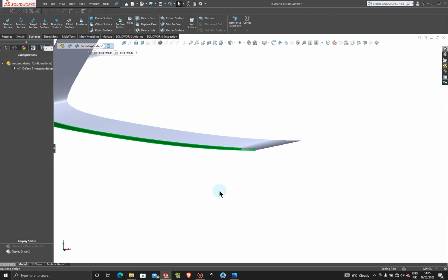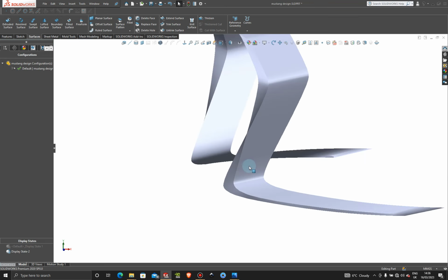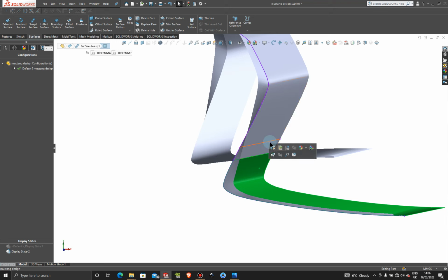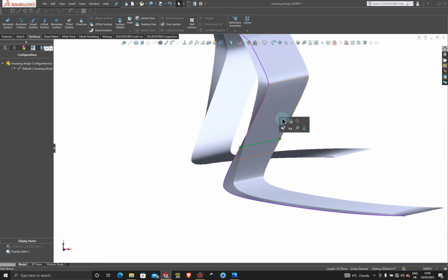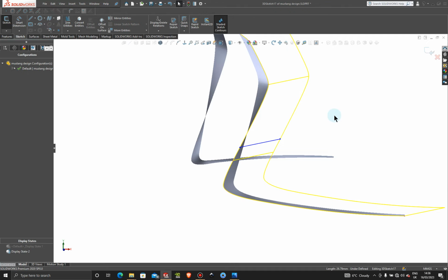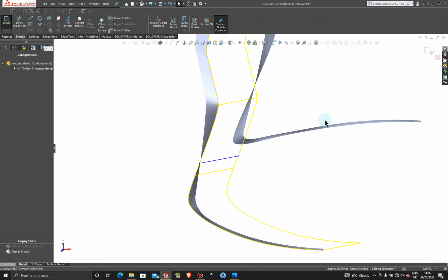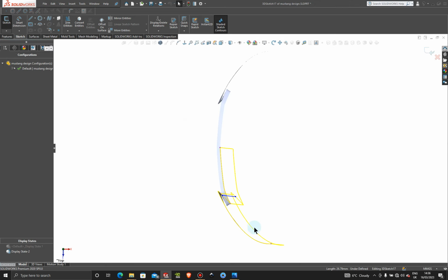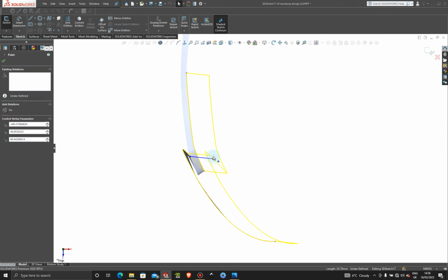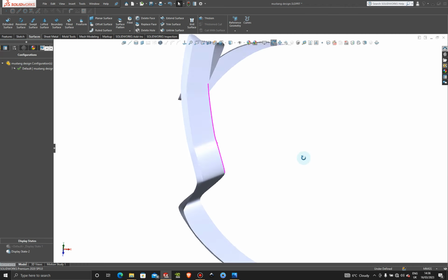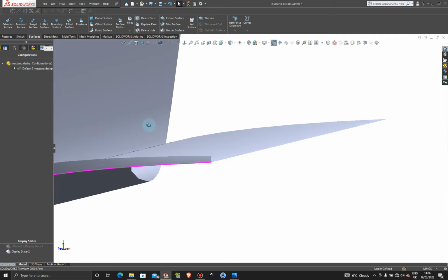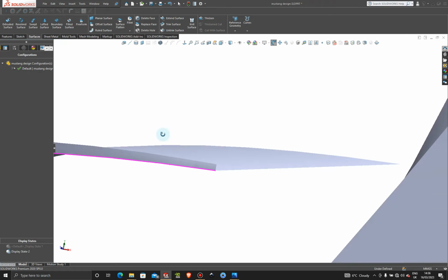So we're gonna fix that by clicking on this surface here, and then our control line is this one here. I'm gonna click on that and say edit the sketch. I'm gonna press space over here, jump to the top, and because the angle drafts too straight this way, that creates a bleed here. So actually I'm gonna add that draft a little bit this way, and then we're gonna have a look. So much better. Our bleed is completely gone.